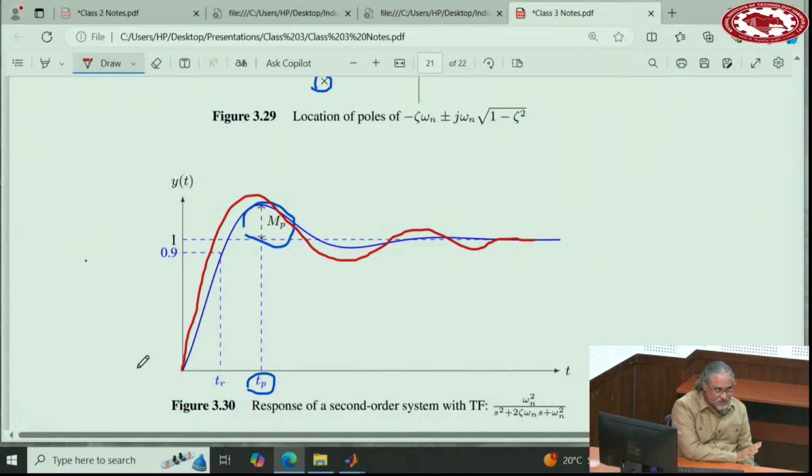For the first order system, there is no ambiguity. But for a second order system, there is an ambiguity. We cannot simply say this is faster than the other one. You need to explain in what sense. If you mean in terms of rising to the final value, yes, the red one is faster. If you mean in terms of settling to the final value, no, the blue one is faster. So these terms should be used carefully as researchers. Don't use them very loosely; use them adequately.